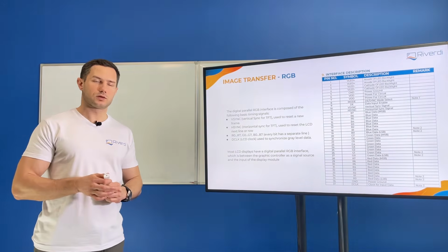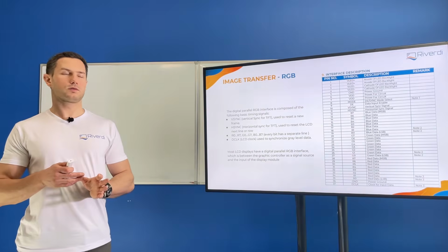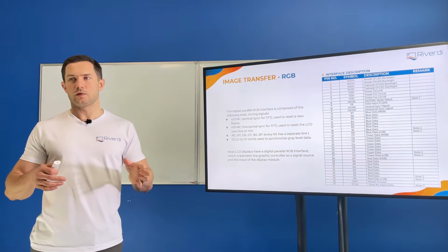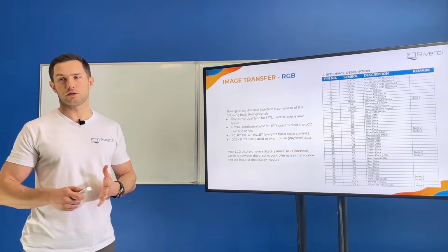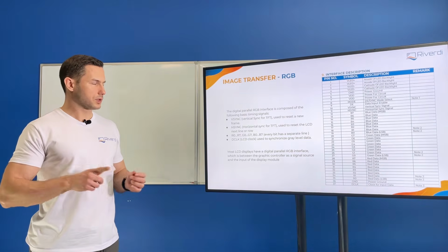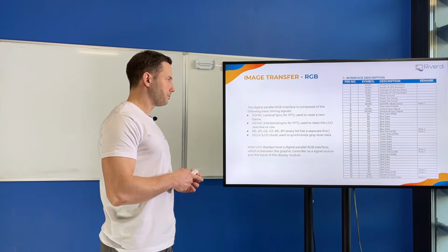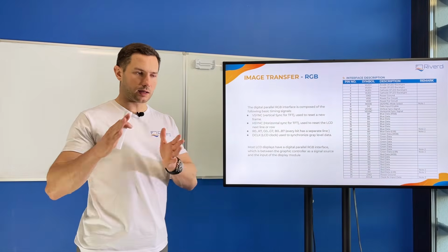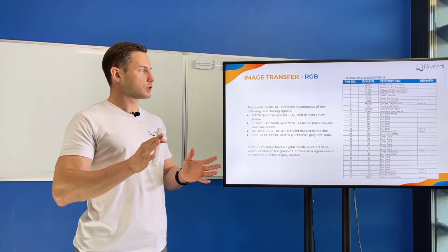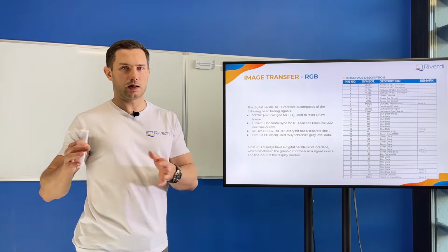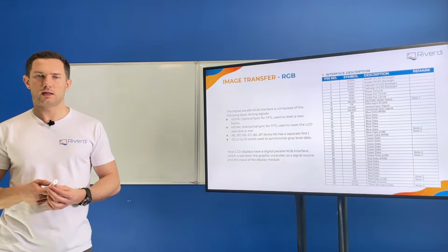The 12-inch is the total maximum, but if you want to find a 12-inch with RGB interface, the resolution will be lower, usually like 800 by 600, so very low for this size of display. That's why 7-inch is usually the size where displays switch from RGB to LVDS, and you can see this in our products.